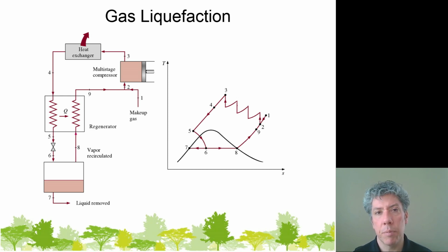Now I know it'd be either nitrogen or oxygen; I can't remember which one would liquefy out first. But anyway, if we could pass state 4 across a heat exchanger so that the gas that's returning to the compressor to be recompressed absorbs some heat, then we could cool down the gas, and that really is the heart of this system, what's called a regenerator.